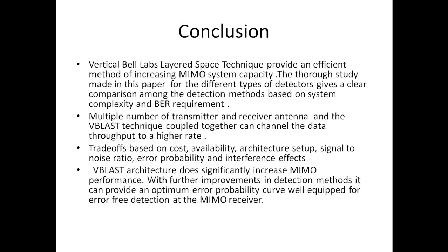So finally, we'll conclude. V-BLAST is a very efficient technique of increasing system capacity in MIMO. We've come across different types of detectors which are used in V-BLAST to improve its performance in this particular project. V-BLAST can help to channel the data to a higher data rate when coupled with MIMO. And you have your trade-offs based on cost, availability, architecture setup, signal to noise ratio, error probability, and interference effects. V-BLAST architecture has still a long way to go. It has scope for higher improvement wherein it can achieve very high throughput and capacity, and it can be made to achieve error-free detection in the MIMO receiver. So that's it from me. Thank you.